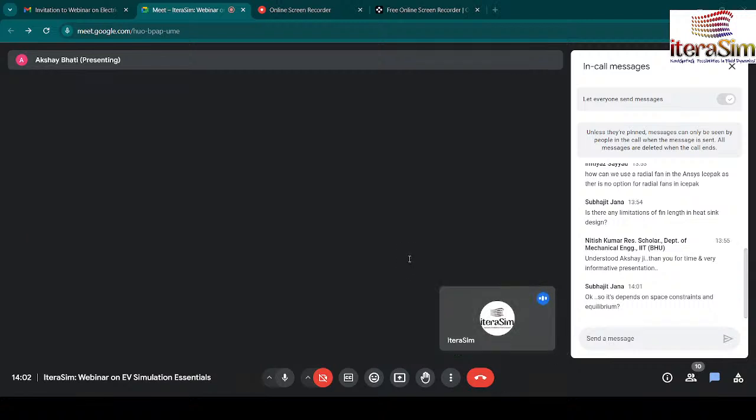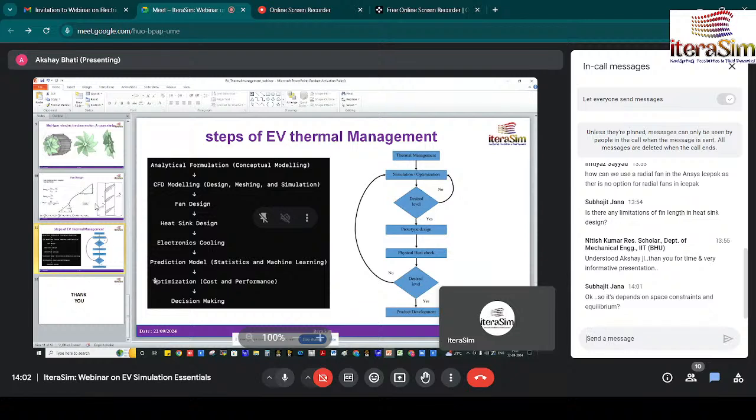So Akshay, I have a question. You have discussed various cooling systems. There is another one that you discussed, the solid state cooling system. Solid state cooling means we provide a highly conductive material in solid form to conduct the heat from the heat source to some other part. For example, you want to conduct the heat from the stator of the motor to the motor casing, because heat mostly dissipates from the casing using air or any fluid.